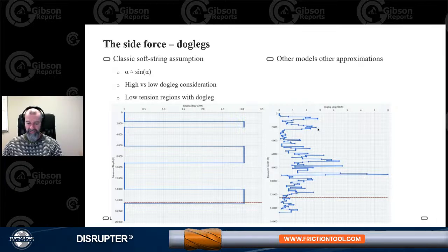We see perhaps tortuosity, but also general steering as well as possible. It looks like they've done a reasonably good job. The changes aren't that big, about a degree per 100 feet, apart from a small section down at 9,000 feet, where we suddenly see a big jump in the doglegs going all the way up to 8 degrees. So quite a lot more than our parametric well, which doesn't have more than 3.